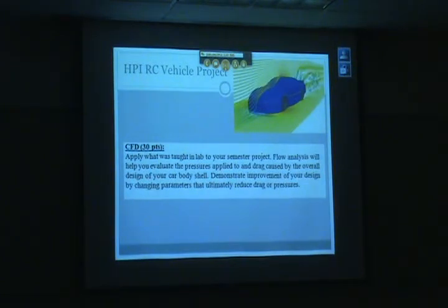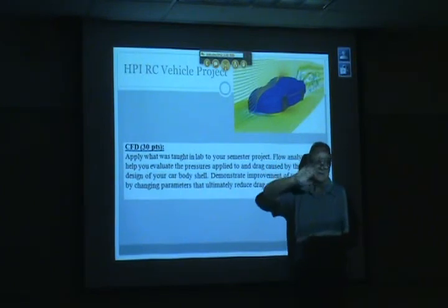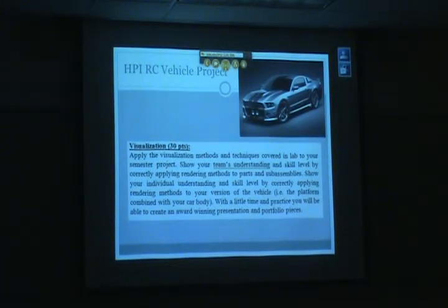We will want you to consider and look at some CFD. Now the stuff that we do will be not the full body of the car. We'll just take a slice down through the car. So we'll take a planar cut and we'll do a 2D CFD analysis. But you will learn how to put on boundary layers. You'll learn how to set far walls, near walls, inlets, outlets. You'll learn how to set up the problem and do a basic solution of your car.